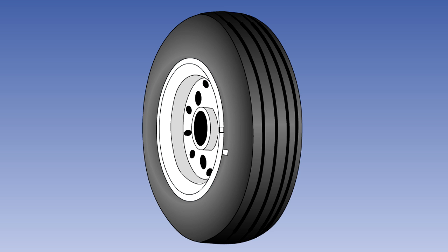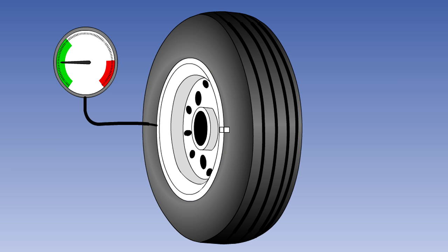If this creep is excessive on a tyre fitted with an inner tube, it will tear out the inflation valve and cause the tyre to burst. Creep is less of a problem with tubeless tyres, as long as the tyre bead is undamaged and any pressure drop is within limits. Creep is less likely to occur if the tyre gas pressure is correctly maintained.